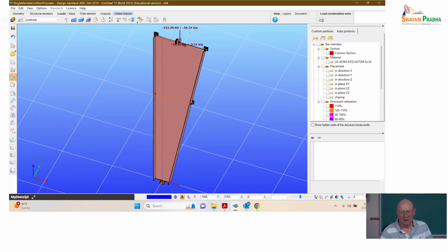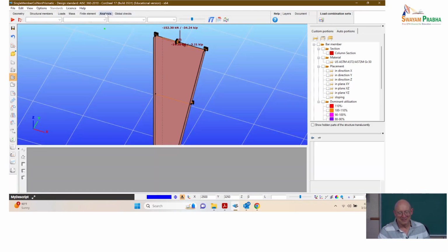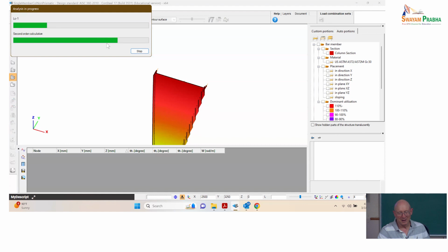Okay. So what do you think? Do you think the flexural buckling out of plane on this is going to change significantly? Any bets? Now you can see up at the top, just to make sure I had a concentric axial compression here along the inclined centroidal axis, I gave it a component x and z and x for the applied load at the top. What do you think? Is the buckling load going to be larger or smaller? Or the same? You're not going to say. Larger. Larger. Let's see. So we'll run it.